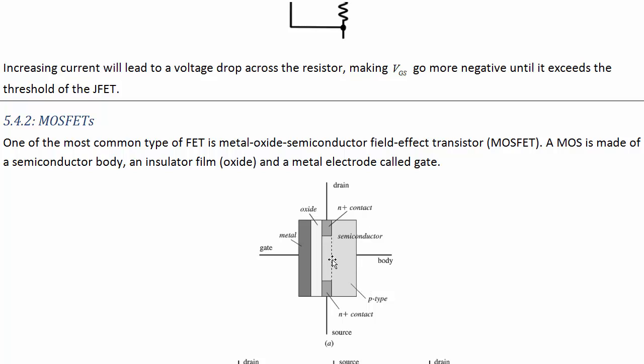And the other change in the MOSFET is that we've got N plus and then a P region and an N plus region at source. So that means that we can't flow anything from drain to source. So how does this work? Well, we have to apply a positive gate voltage to cause these holes to flow out of there, and the minority carriers, the N carriers that are in here, to accumulate next to the oxide, creating an inversion of the semiconductor that makes an N channel. So this is an N channel MOSFET.